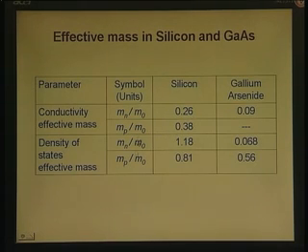So in density of states effective mass, you should not invoke the concept of movement. It is some different average used to represent the quantum mechanical situation. We will not discuss this point any further. The only thing you need to remember is effective mass depends on the situation. So you must use the appropriate effective mass. The values are shown here for gallium arsenide. This value here is not shown because for the exact value there is no agreement. That is all it means, not that there is no hole effective mass for gallium arsenide under the conductivity situation, it is not that.